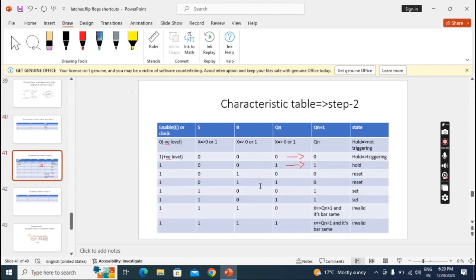Here reset is coming. So reset means value 0 0, in both cases 0 0. Observe once, this 0 1 is going to the gated part, not to the latch part. But the latch part is getting 1 0. That's why reset. That you have to observe.